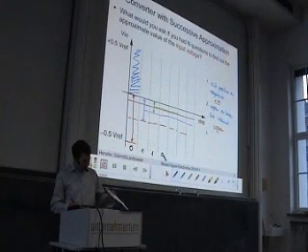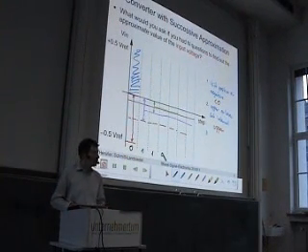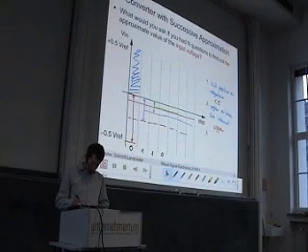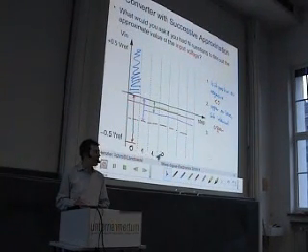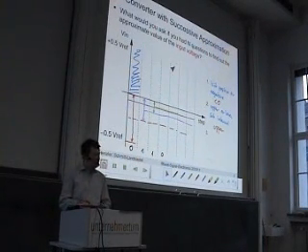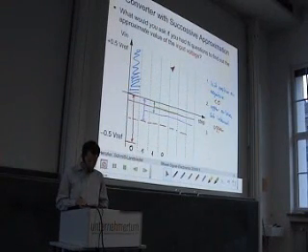Interesting is that if we have the lowest possible value, so if we are below all thresholds, if we are somewhere here, then all the output bits are 0. If I have a very, very high value, then I'm always above the thresholds, and this means that all the output bits are 1.